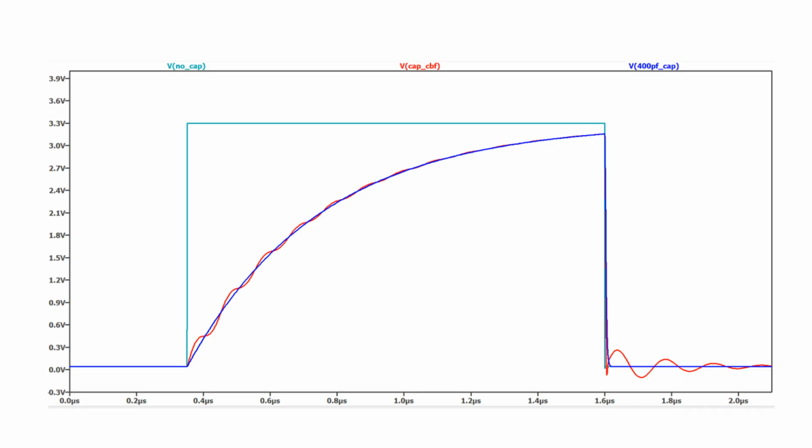The simulation result shows that practically no influence on the rise time of the signal can be expected from the multi-layer surface mount ferrite. Because each multi-layer surface mount ferrite also has an inductance component, minor oscillations are visible in combination with the bus capacitance. However, these are not critical because their amplitudes are less than 10% of the actual useful signal. In the real measurements, these oscillations are significantly lower.